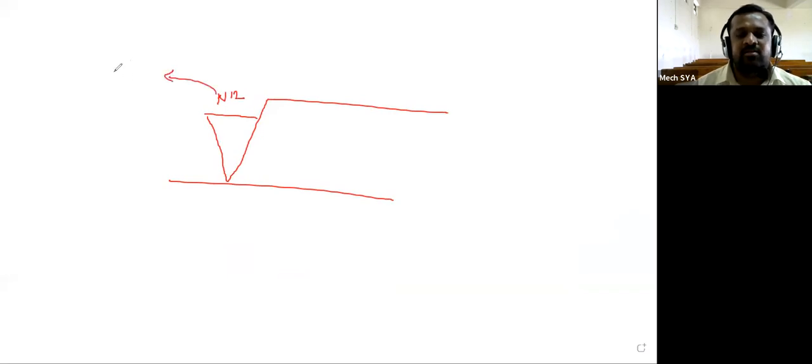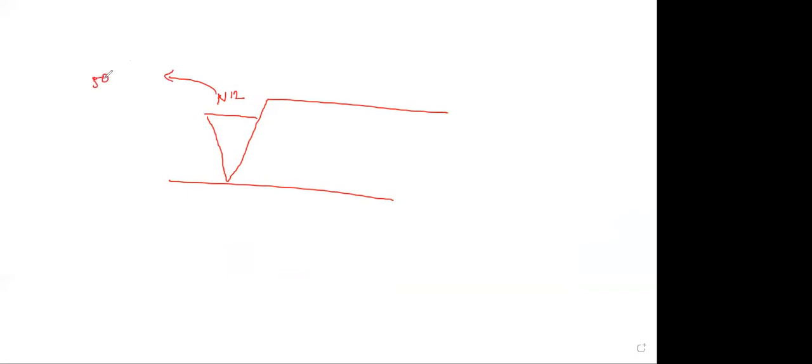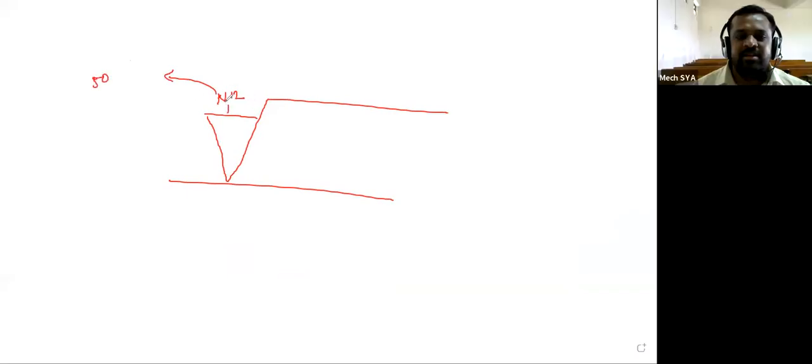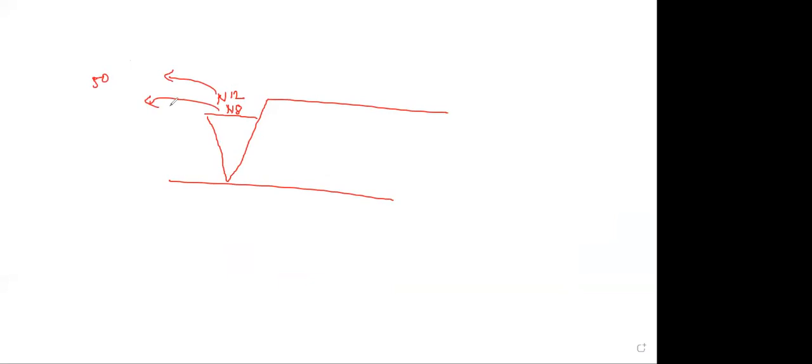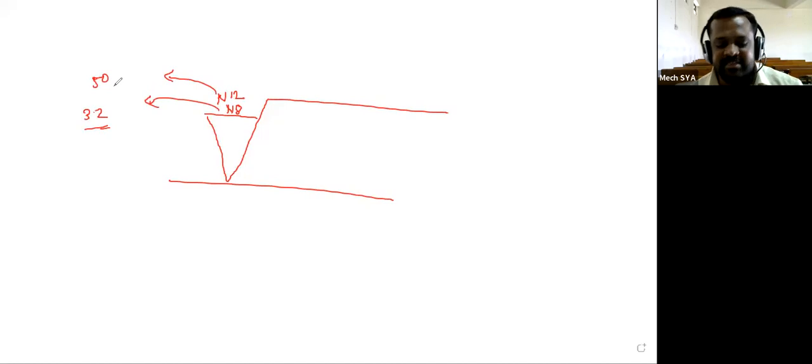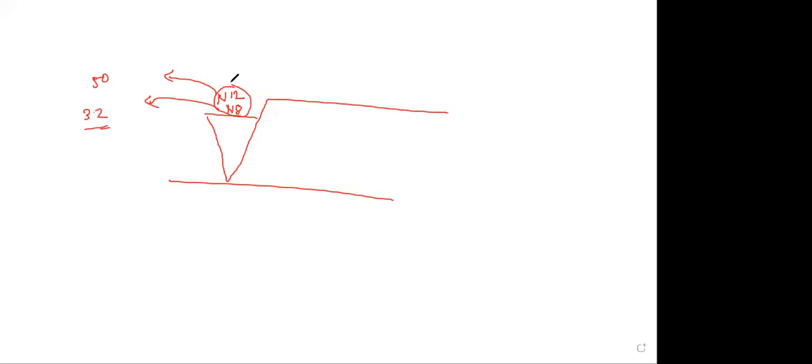Yes. What is the surface roughness value? The roughness value is 50. Okay, sometimes they will write down here N8. Then tell me what is the surface roughness value? 3.2. 3.2 like this. Okay, for this purpose the chart is necessary. Understood? Why have I studied this chart? Because in the surface roughness symbol, every time they will not directly give the surface roughness value. Sometimes they will give the grade, sometimes they will give the symbol also. According to that, we have to select the proper surface roughness value. Okay, understood? Yes. Yes, sir.